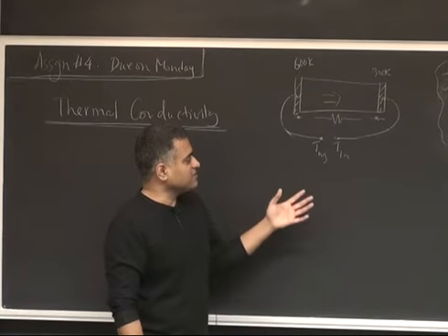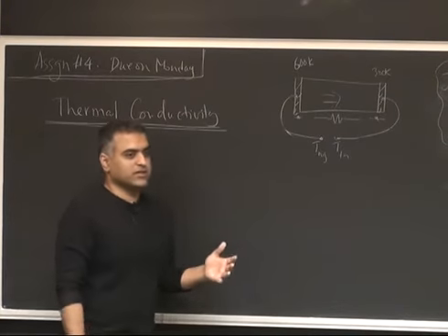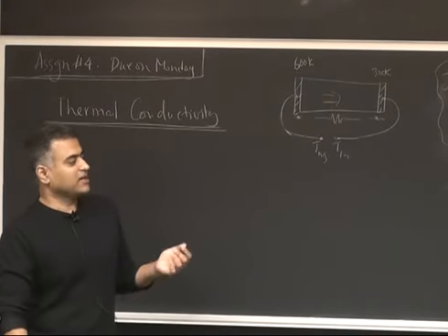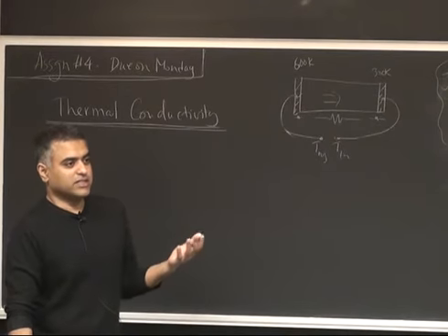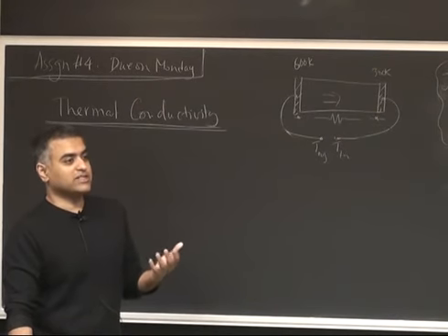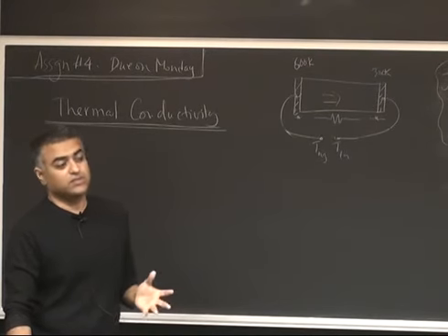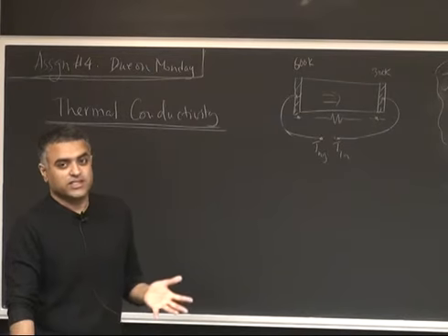So essentially, we have the same transistors. We have transistors today that carry about the same current per unit width, but they are today 10 nanometer in dimension compared to 10 microns a few years ago. So they are generating the same amount of heat, but in much smaller volumes now. So getting the heat out is extremely important, and it's a very big challenge right now.